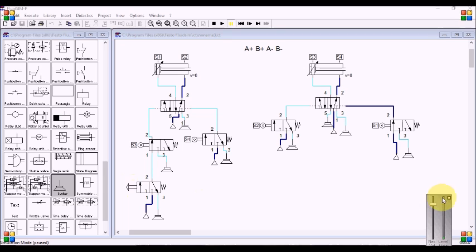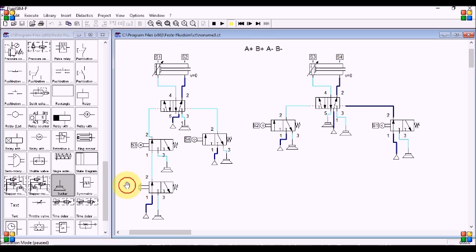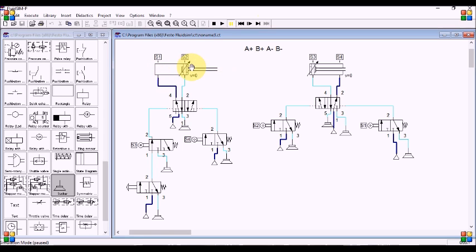In the step by step video, I can just press it. See, now you can see a blue line wherein it's making it possible to move the air from here to here. In the next step, it has moved. You can see here, this position has shifted. Now air would move here. It moved and S1 has moved to S2. Meanwhile, make a point that as it is a spring return, this has got its position shifted.